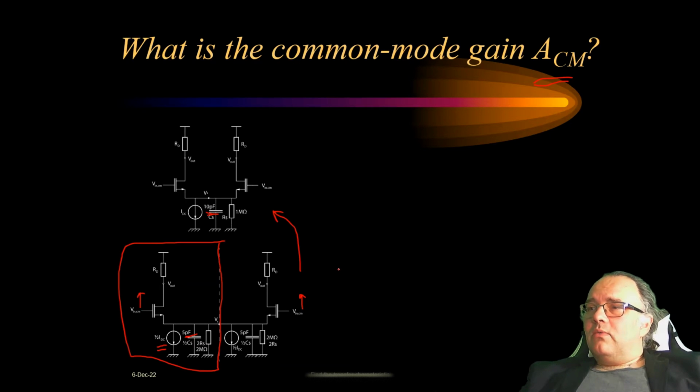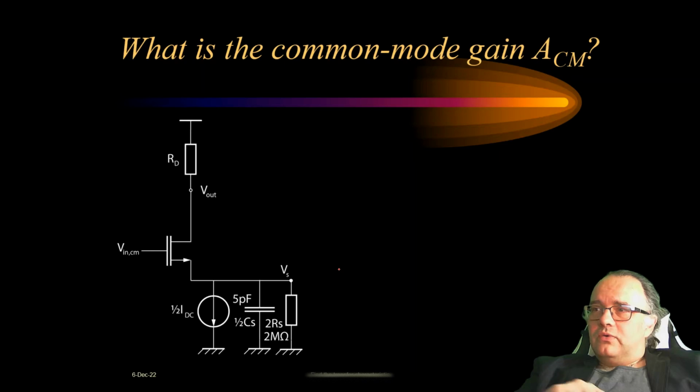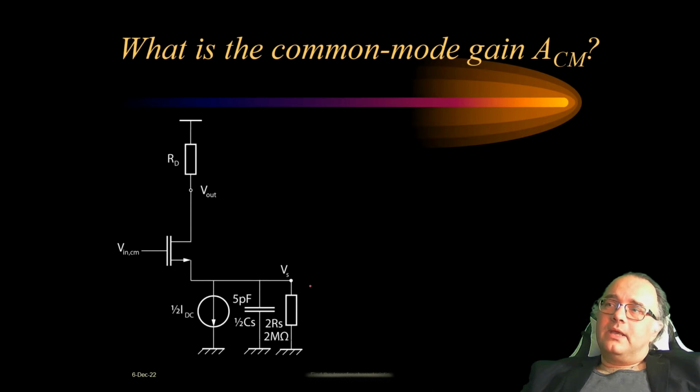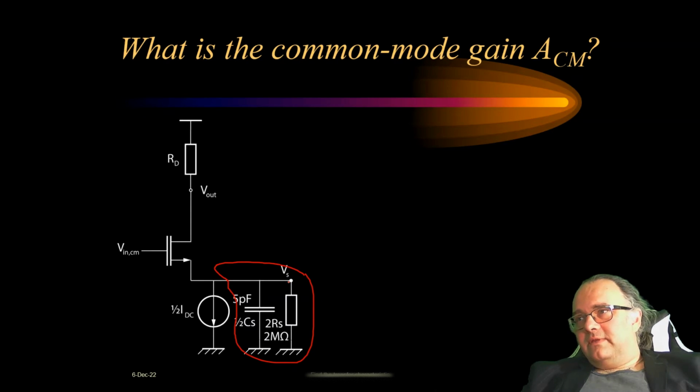So now what we have for 1/2 is shown here, and this is the circuit we call common source with source degeneration, in the sense that this here, for small signals, acts as negative feedback.